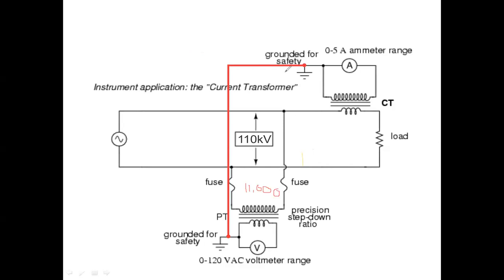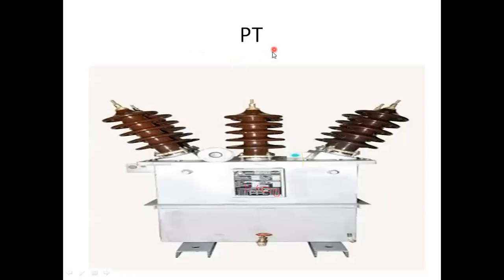Today our topic is PT. This is the potential transformer. And now you can see this is a photograph of a potential transformer. A potential transformer is generally used to measure the voltage in a transmission line. Not for our normal, conventional cases, but in a high transmission line, an 11 kV or normal distribution line. In these cases we have to measure the voltage.